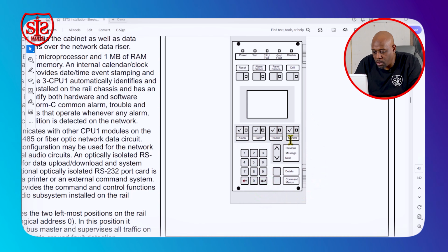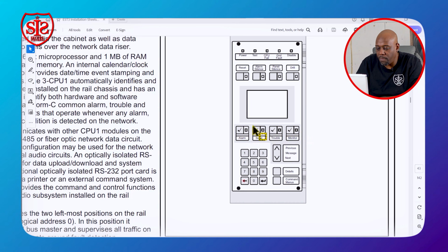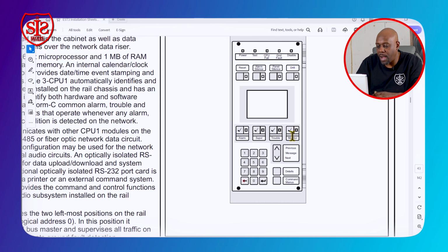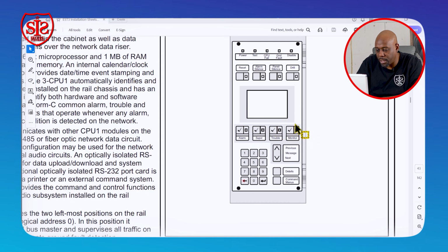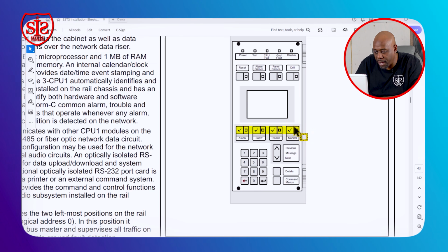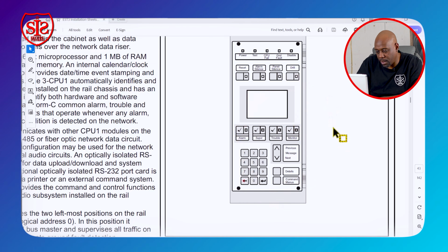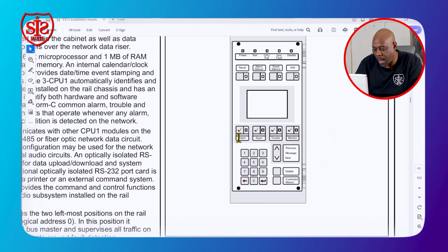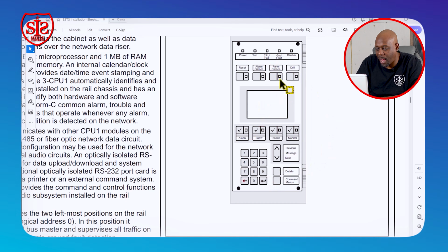These alarm, supervisory, trouble, monitor, these are LEDs. So whichever event, alarm event, supervisory, trouble, or monitor event happens on a fire alarm system, this LED will flash. And you have to hit that check button to acknowledge each and every one in order for this LED to stop flashing. If you just want the panel to stop making noise, because it's beeping, other than the alarm that's activating the horns and strobes, you hit the panel silence button.